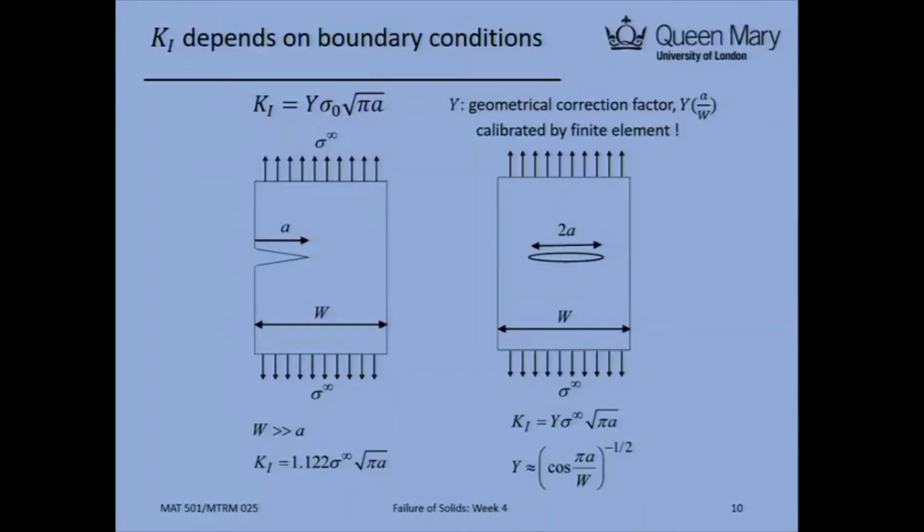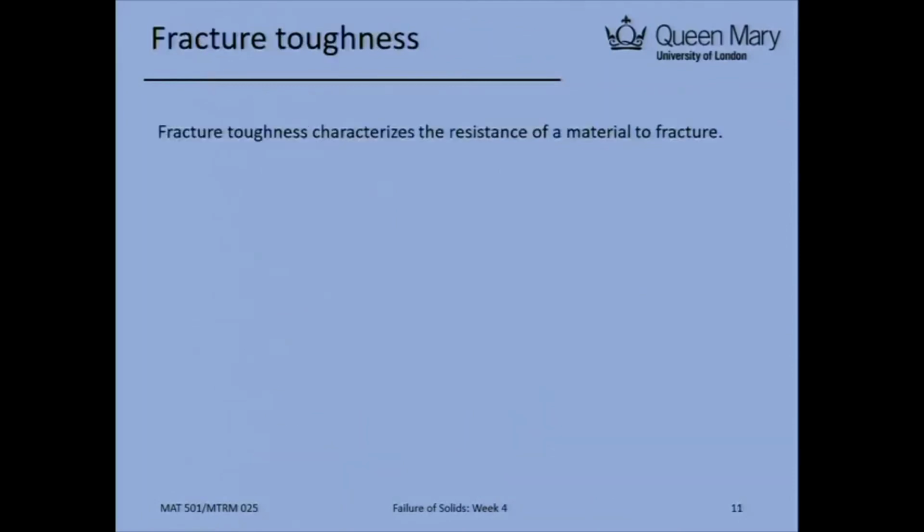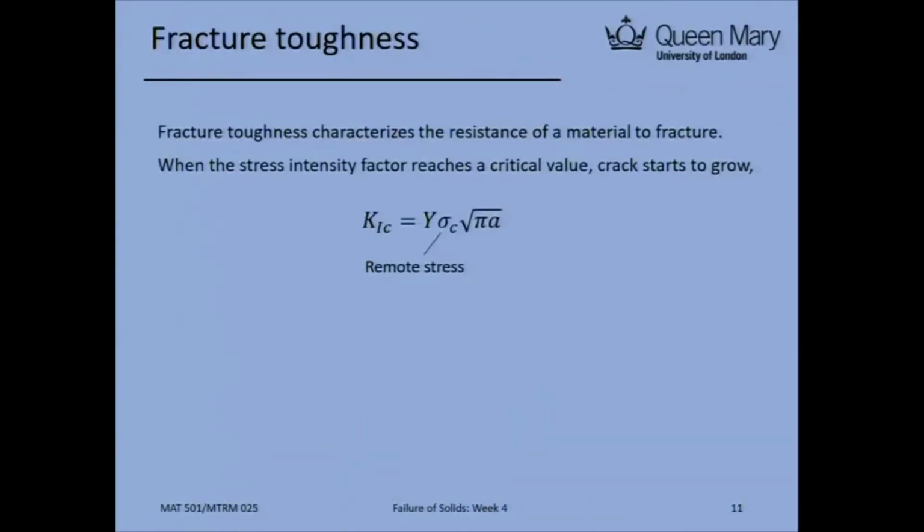Otherwise, you always need to remember, divide your total length by 2. For this type of case, you just think about A, that is enough. But this one, you need to cut them into 2 pieces and think about that only half of the crack length will generate that stress concentration on the tip. Okay? So most of my definition for this fracture phenomenon is by using 2A, a double that. But when you look at the equation, K, there's only A here, right? Because you need to think about half of them are doing the job.